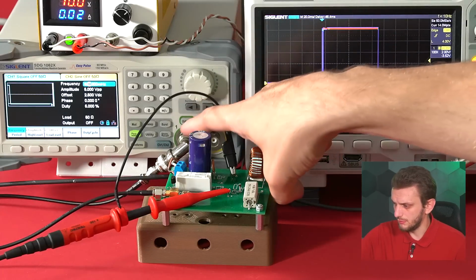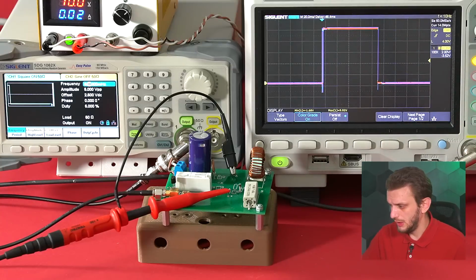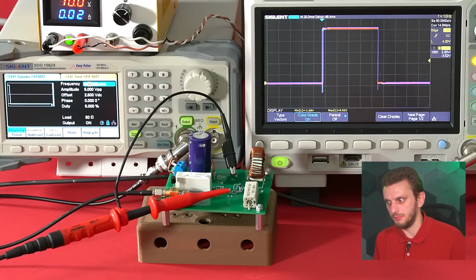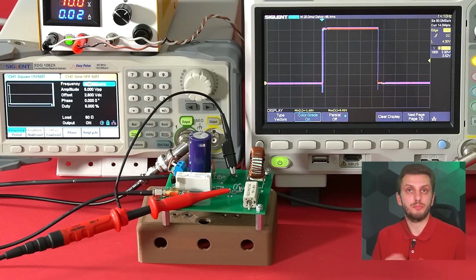So if we let the circuit run for a while, well, nothing really breaks. So this works just fine. Anyway, in datasheets of components designed to actually take some amount of power, so not really small signal diodes, you will get proper graphs highlighting their pulse handling capabilities. So how much power and current they can handle for short periods of time. So that way you can make sure that the component will work correctly in a long-term use case.